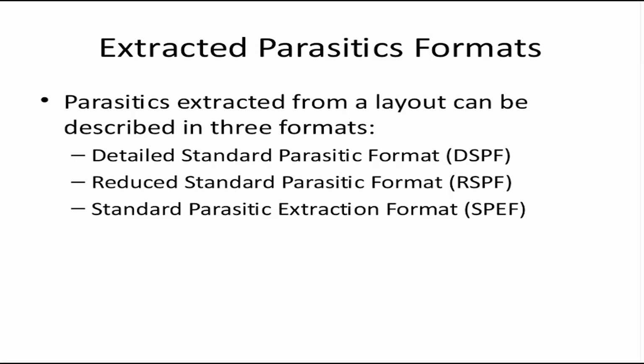After routing, when the physical data is completely generated, GDS is generated, there are extraction tools which work from the layout. Now the layout has all the information about all the nodes and cell placement, right? So one of these tools is called StarRC XT from Synopsys. This tool will read in the layout data. It will read in the technology specific files, which have the information about the thickness and the coefficients for different metal layers. Using that data, it will generate the parasitic file.